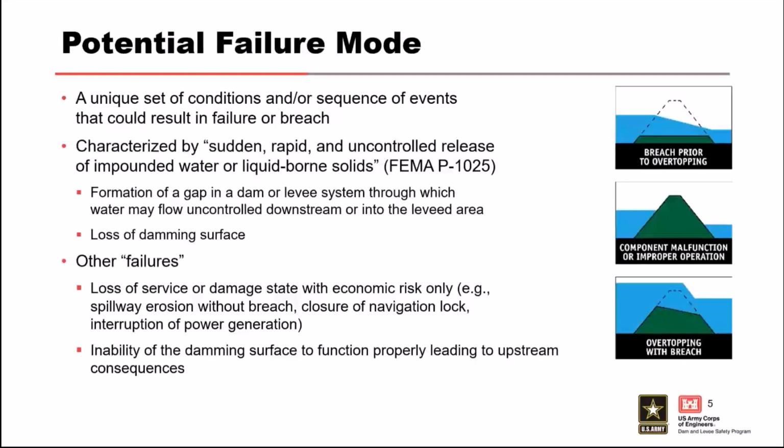According to FEMA 148, it's recognized that there are lesser degrees of failure in that any malfunction or abnormality outside the design assumptions and parameters that adversely affect a dam or levee's primary function of impounding water is also properly considered a failure. These lesser degrees of failure can progressively lead to or heighten the risk of a catastrophic failure. They are, however, normally amenable to corrective action such as successful intervention.